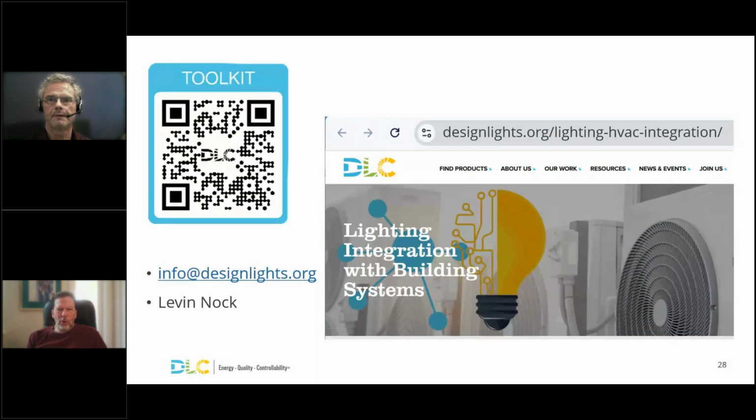Well, that's actually an interesting question because, in my opinion, it's not necessarily the control manufacturer that does that, but the controls integrator or the master systems integrator. Any controls manufacturer that's using an open protocol like BACnet can receive information from the lighting system. So it's not a question of the capability of the tool set. This would be the BMS front end, the building management system. It'd be more the question of, does the integrator who's actually integrating the job have the technical ability and the skill set to be able to take that data and do something intelligent with it?